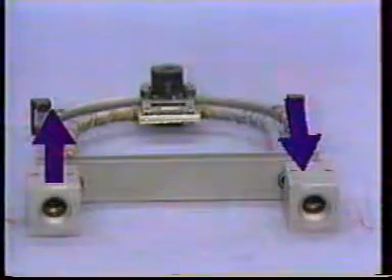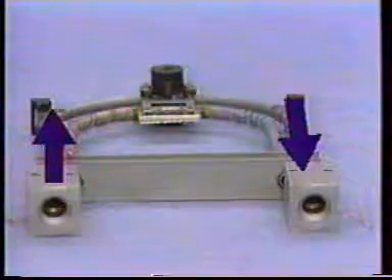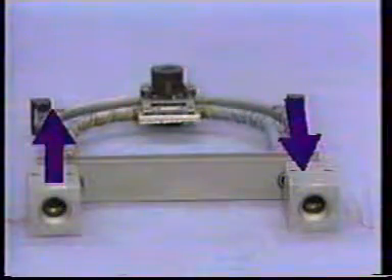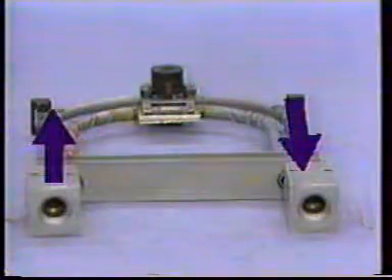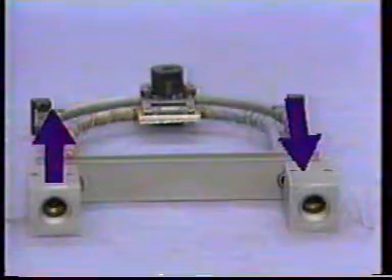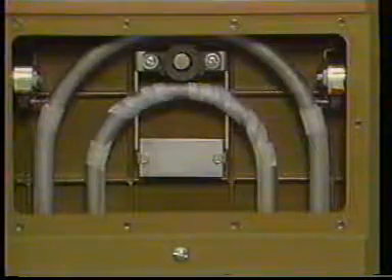The result is that a Coriolis acceleration is induced in the flow, tangential to the axis of rotation and perpendicular to the flow path. However, because the angular motion is oscillatory, the direction of the acceleration alternates. The accelerated flow exerts a force on the walls of the tube. Since fluid is flowing in opposite directions in the two arms of the tube, the direction of the force at any moment will be exerted in opposite directions, upward on one arm, downward on the other. These forces produce a twisting motion in the tube.